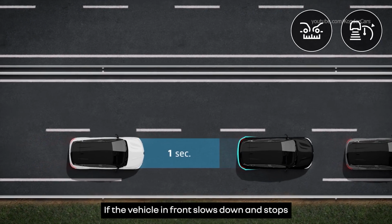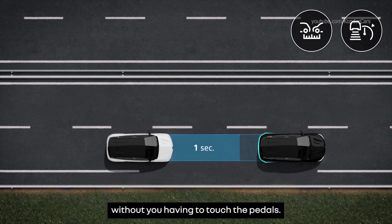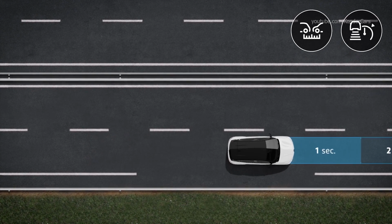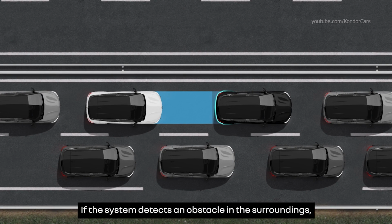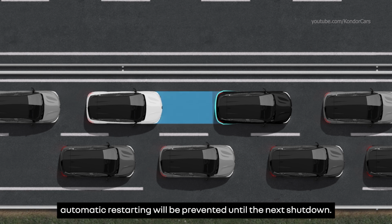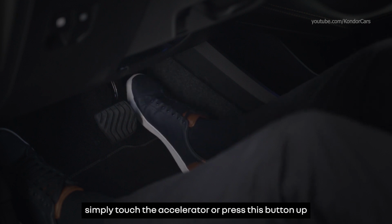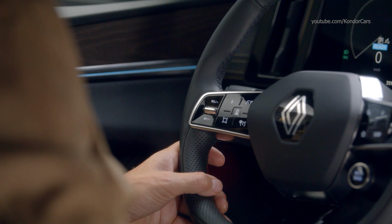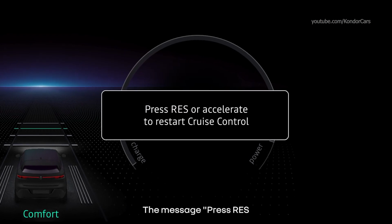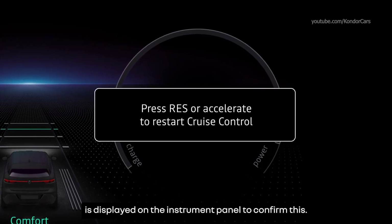If the vehicle in front slows down and stops for up to 30 seconds before moving off again, your vehicle will do the same without you having to touch the pedals. If the system detects an obstacle in the surroundings, automatic restarting will be prevented until the next shutdown. If the vehicle restarts after 30 seconds, simply touch the accelerator or press this button up to move off. The message "Press Res or the accelerator to restart cruise control" is displayed on the instrument panel to confirm this.